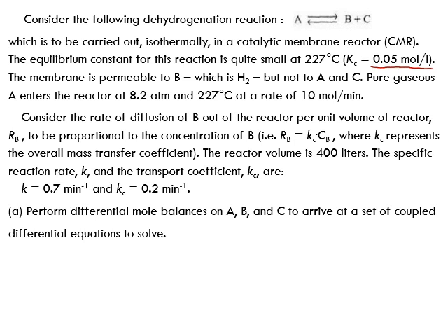Therefore, we use molar flow rate since we have a gas phase reaction, which means we have to derive and use 3 mole balances written in terms of molar flow rate, because we have 3 species. I'm going to skip the step because we have already derived the differential mole balance for the diffusing component, which is B in this case, and the non-diffusing components, which are A and C.